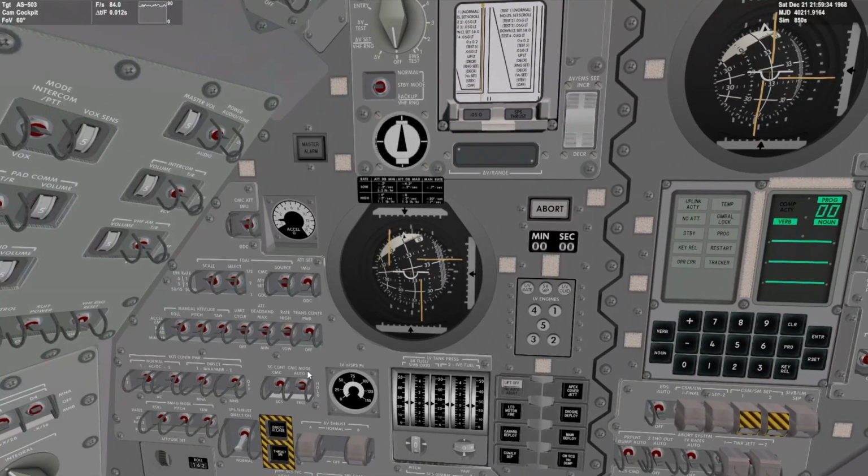We're in rate high SCS. If I wanted to time warp while I am in PTC, I would switch control from SCS to CMC free, which will completely eliminate any sort of deadband area. So the thrusters now will not fire to correct our position.